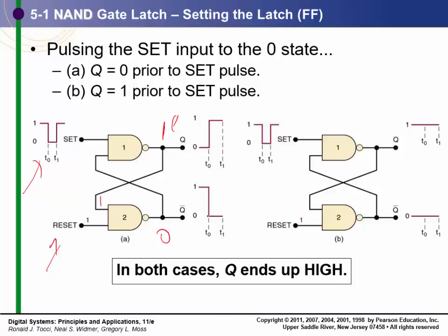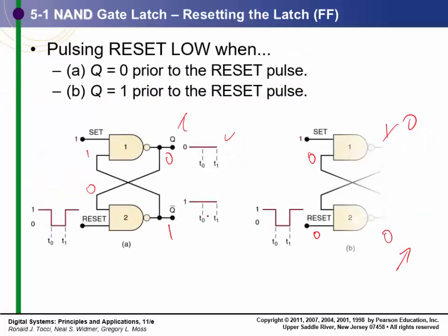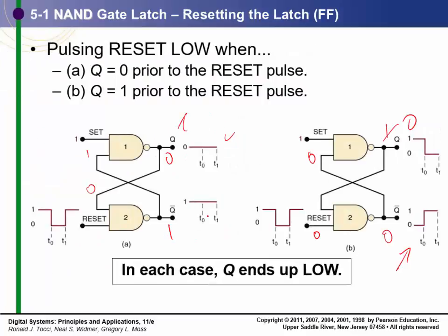So this is called an SR flip-flop. We can change its state by pulsing one of the two inputs. There are other SR flip-flops that use active high pulses. So this is the basic SR flip-flop. It's the building block of the rest of the flip-flops we're going to talk about today.